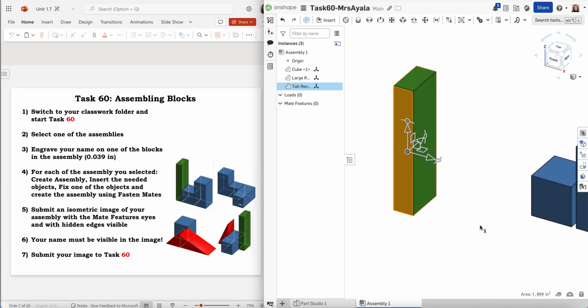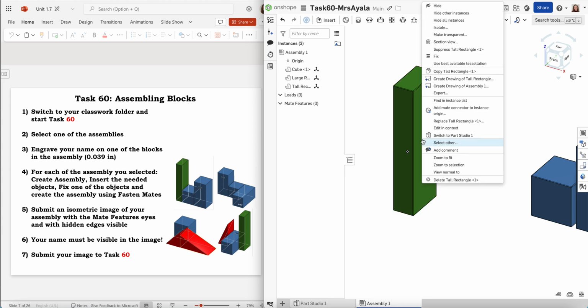Let's see, so that looks good. I'm going to click off of the block now in the white area, and I see my block is in fact on the origin. Now that it's here, I'm going to hover over the block, and I'm only going to right click on it. I'm not using my left click button. And that gives me the option to fix.